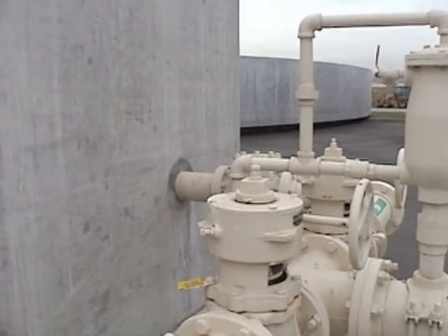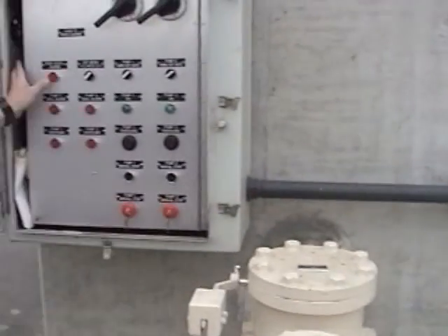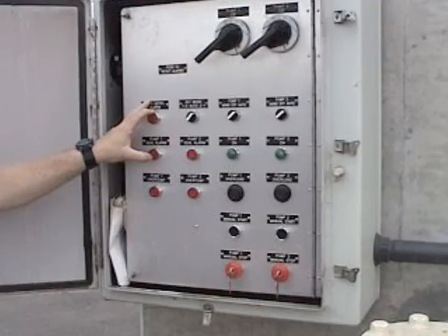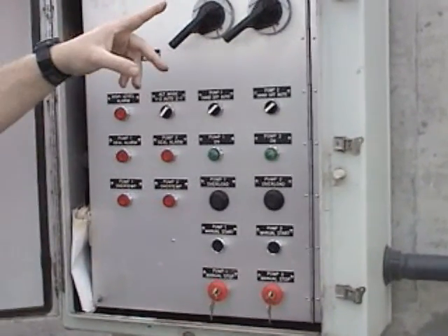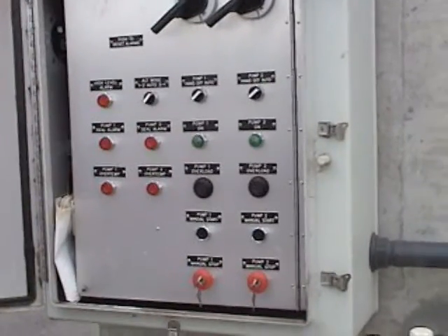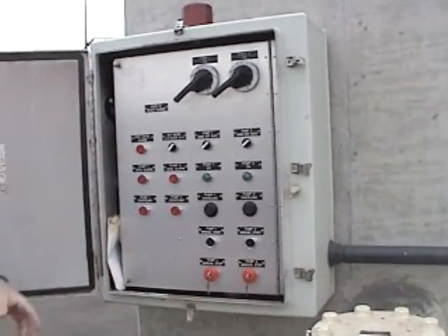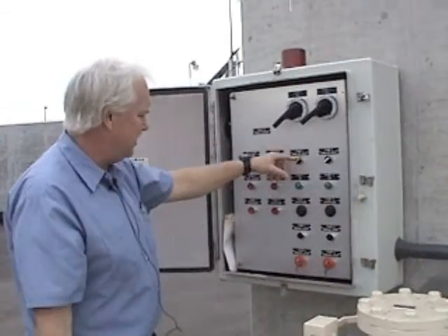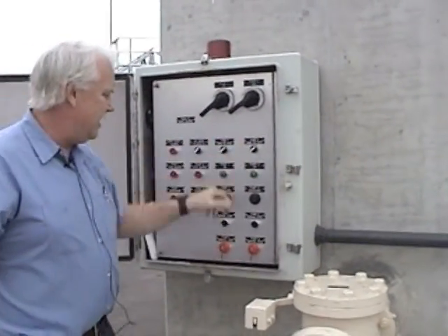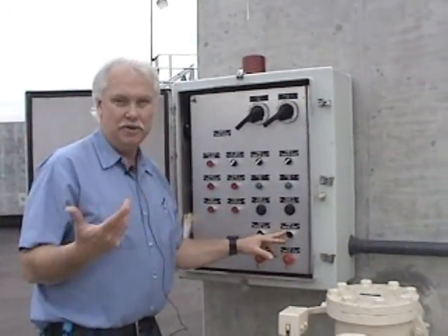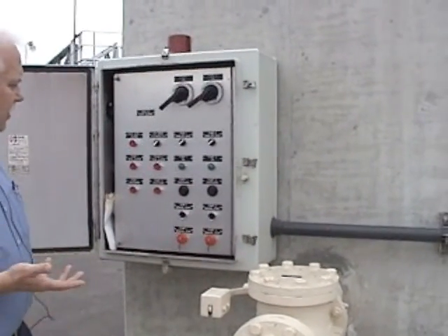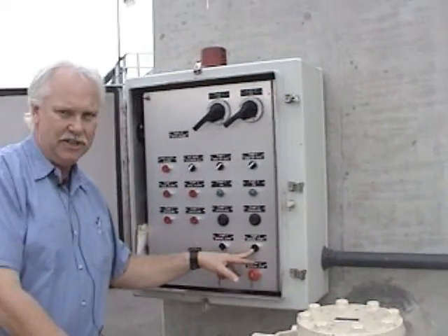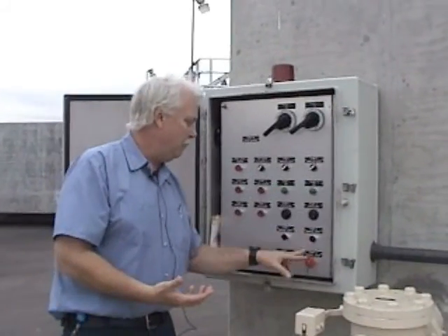So you'll have a high level alarm, which is this guy right here. You'll come out here and you'll see that this is lit, and you'll say, well, I've got a high level alarm and the pump isn't pumping. It's probably the float is either wrapped around something, or the solids are so thick that it can't float and start the pump. If that's the case on this particular pumping system, a lot of plants, you can put it into hand, hit start, and it will run. This won't do that. In order for this pump to start, even in manual, that float has to be free. If it's hung up on something, this pump will not start even in manual.